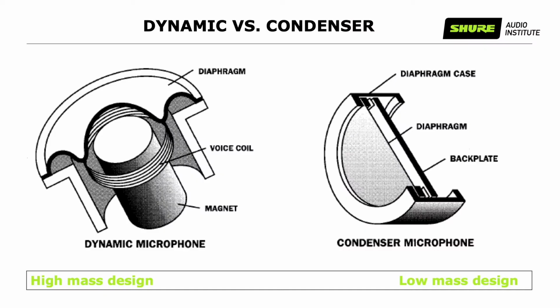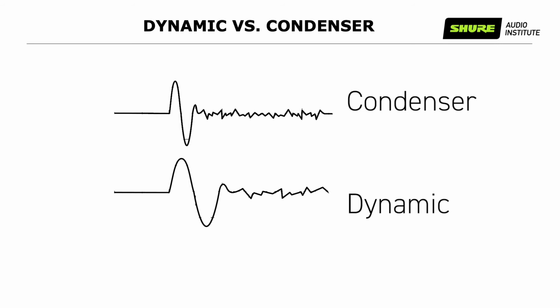Now, condenser microphones respond more quickly than dynamic microphones. So one has a diaphragm with something attached to it, and the other one has a diaphragm with no weight attached to it, right? So that means one is actually lighter than the other. So that means one is actually going to move faster than the other one, which is quicker. So the condenser microphones actually tend to have more response to fast attack instruments, percussions, cymbals, acoustic guitars, toys on stage, shakers.